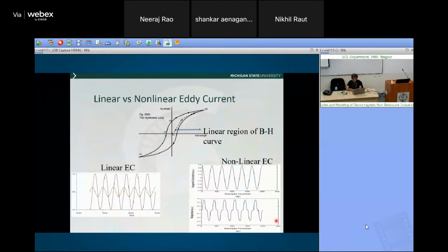So it's a data-driven thing. Based on the harmonic features, using a lot of calibration samples, depending on the harmonic content in this, I know what the defect depth is. So at each depth, along the length, I can determine that.